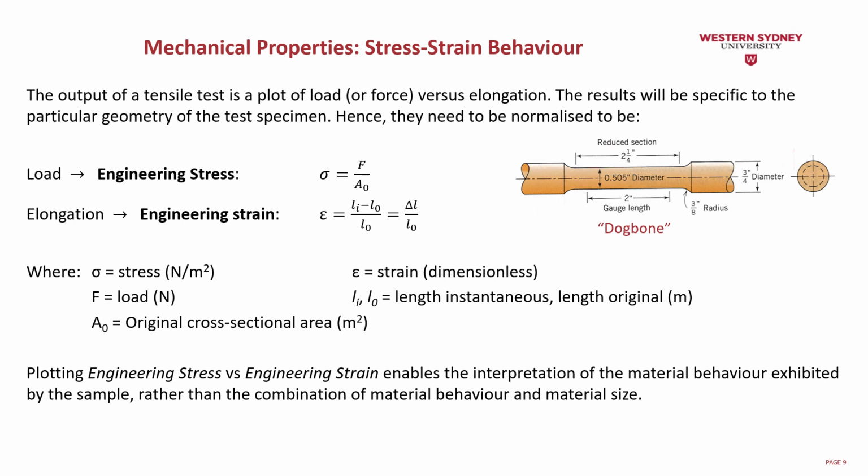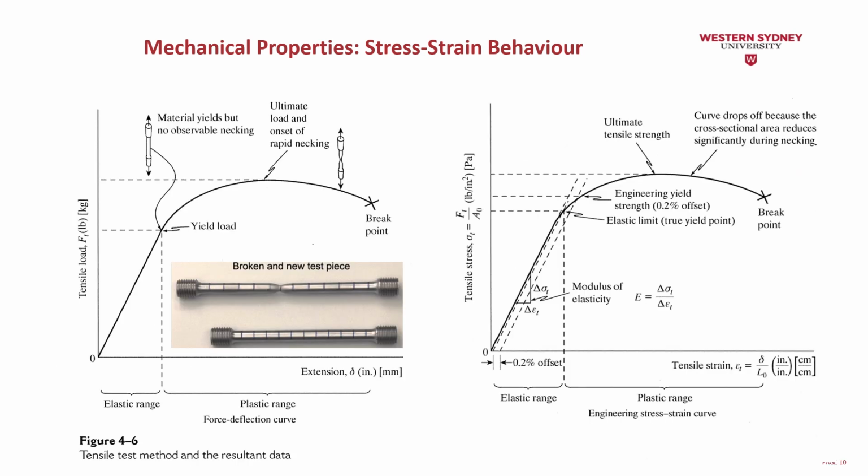So the stress strain diagram will look like the following. As you can see here, we are going to have two stages. We are going to have one before the yield point, which we call the elastic range. And in this range, we're going to have the modulus of elasticity to control the behavior of the materials according to what is known as Hooke's law.